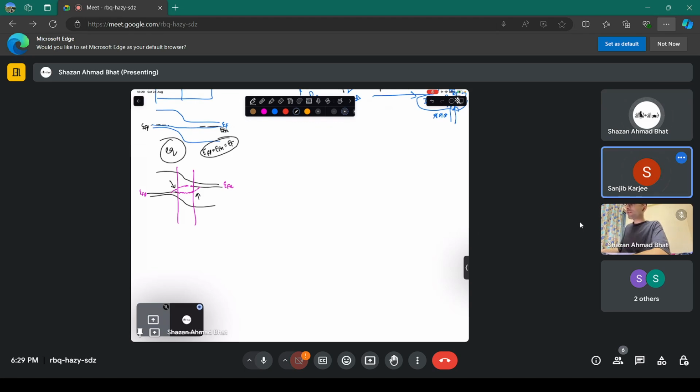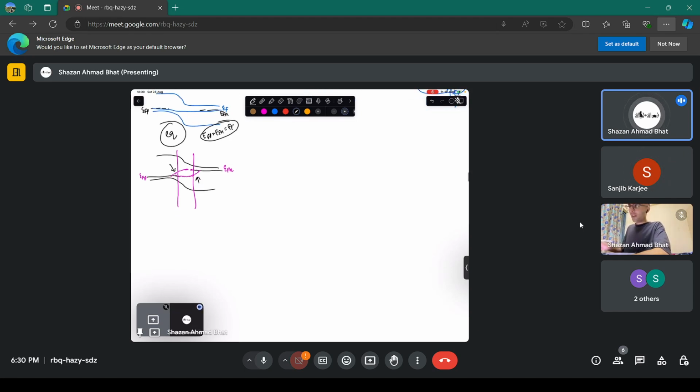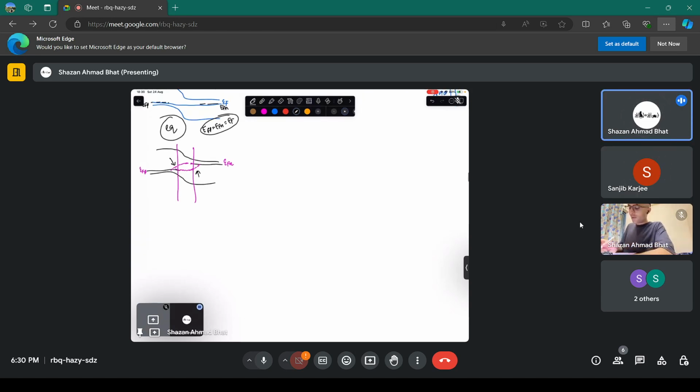This is a very, I should say, a topic or a region where people are mostly confused. And if you understand this thing when you numerically simulate the particular diode or the electrostatics of a diode. But I will tell you in a layman sense, what happens is that most of the diffusion, or the electrons and holes diffusing, or I should say the current flowing, happens at these particular regions where the barrier is basically ending. So that's why there is a slope, and it finally joins their own Fermi level. So that's why this particular slope comes.